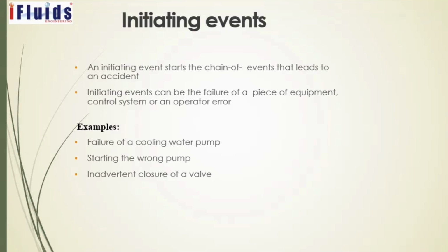Initiating events can be a failure of a piece of equipment, control system, or a human error or operator error. Examples are failure of a cooling water pump, starting of the wrong pump, inadvertent closure of a valve.